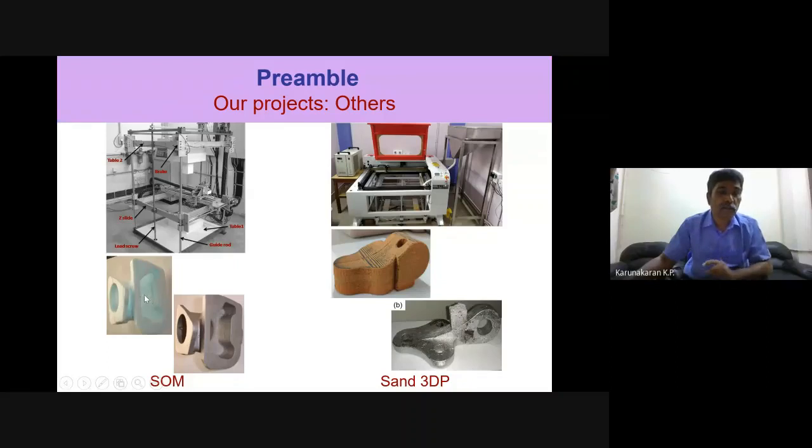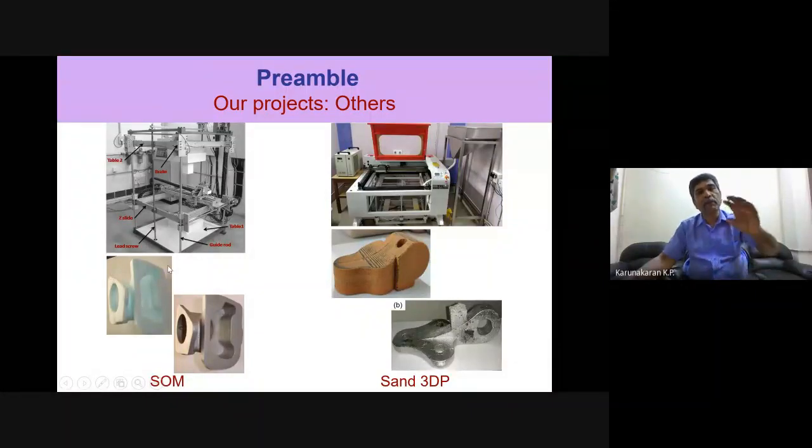So this particular component, it actually doesn't fit into the basic definition of layer so far as we know about additive manufacturing. When you say layer or slice, it will have equal geometry at top and bottom. It will be very thin. Whereas in our case, it is very thick, and the top and bottom geometry of the thick layer is also different. So we didn't want to call it a layer, we call it a segment. Okay, so we call it a segmented object manufacturing.